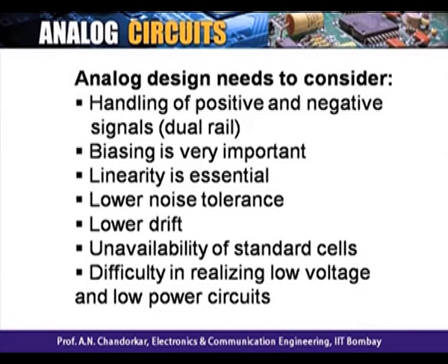The problem with design is, in case of digital, as I said, we can have pre-designed, pre-tested blocks. I have a multiplier, I have a multiplexer, I have an adder. I can design once for a given technology, store it, and whenever needed in a larger circuit, I'll just replicate that. Nothing like that happens in analog; there are no standard cells. Every block you design every time.